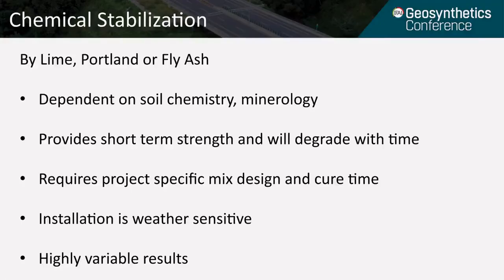For chemical stabilization, mostly this just improves the short-term strength and bearing capacity, and can also help with some of that shrink and swell behavior. However, durability is the major concern, as well as potential health issues. This method is certainly the most time-consuming and weather-dependent, but really what we see is that you begin to experience a breakdown in structure very soon after hardening. So this might be okay where you just need a temporary platform to construct a pad or a road, but you may not want to depend on the durability of your chemically treated subgrade throughout a long duration of use.